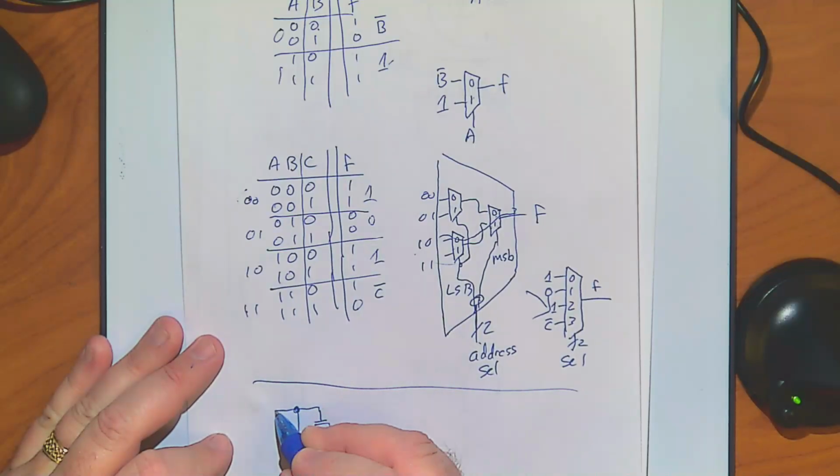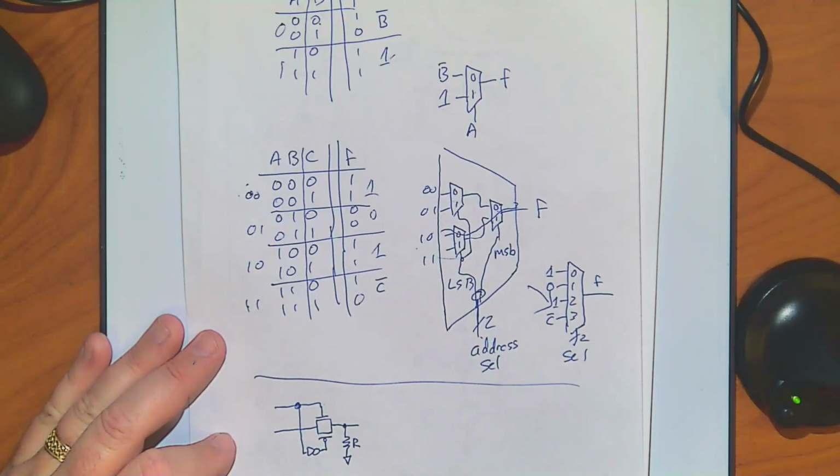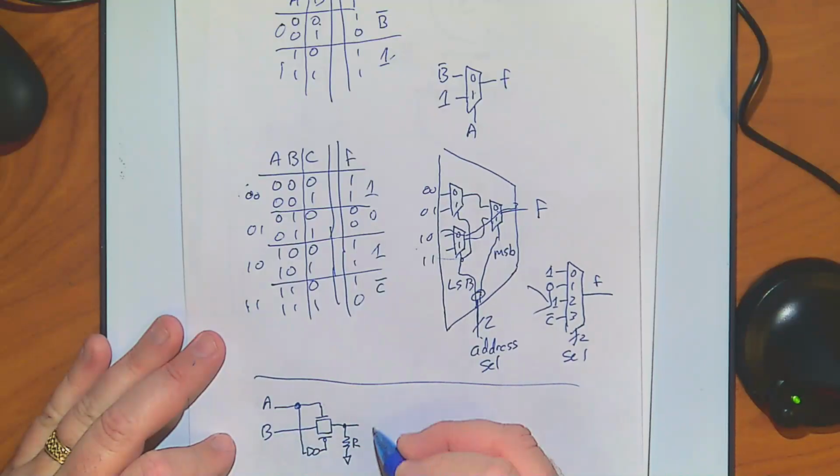All right? So I've got that input and I've got this input. And then imagine on my output here, I'm just going to put some resistor to ground. This is called a pull down resistor. Let me just call this A and call this B, and I want to ask what's F. Now notice, I'm not powering this by straight power and ground anymore. I'm powering it by some signal. That's no problem, it's a select.